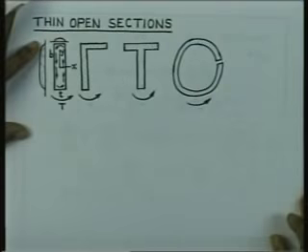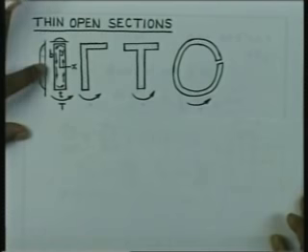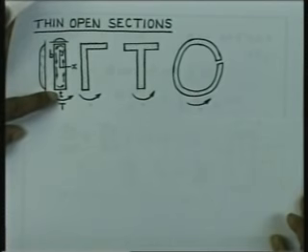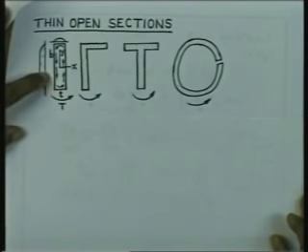So, we have seen the rectangular section, that the stress is more or less constant along the edge of the longer boundary, and it is given by g theta into t, and at the same time the torque capacity is given by g theta into b t cube by 3.